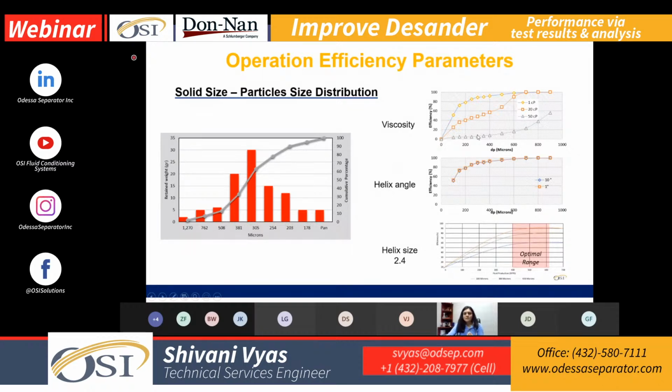Let's say we're talking about 800 microns and now we're at 50 centipoise. We can see the efficiency is 40%, versus whenever we go to 1 centipoise or 20 centipoise, how much that separation efficiency increases for the same particle size distribution.